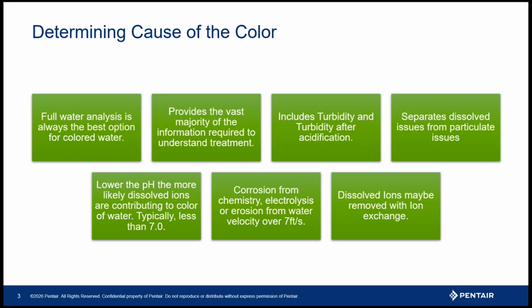We soften water to prevent scale buildup. But soft waters that sit a long time in copper plumbing will dissolve some copper. And this can be quite aggressive depending on how long that water sits. So it's a good idea to flush pipes rather than necessarily treat in those situations, right? But understanding that dynamic.